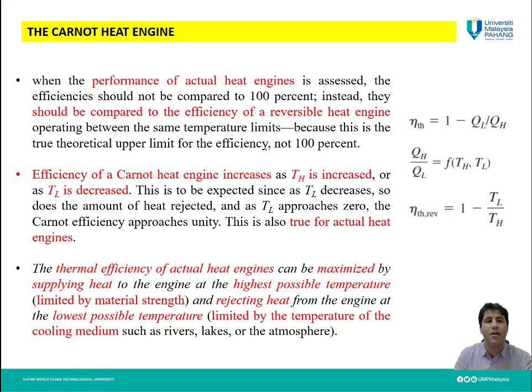So why is this Carnot heat engine important, and why is the thermal efficiency of this Carnot heat engine important? Because we can evaluate the heat engine which we have. We can check for our heat engine how much can theoretically be the maximum possible thermal efficiency.